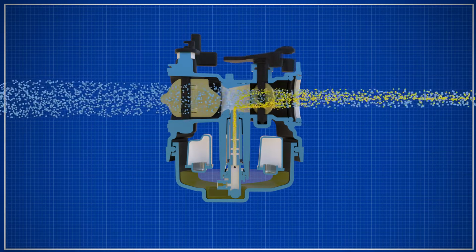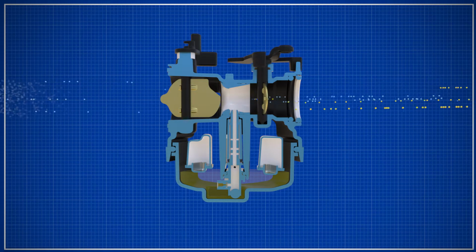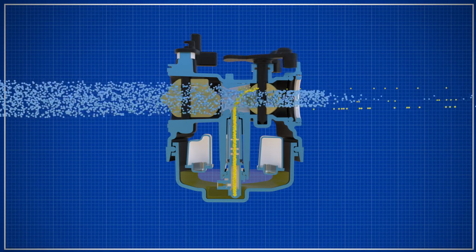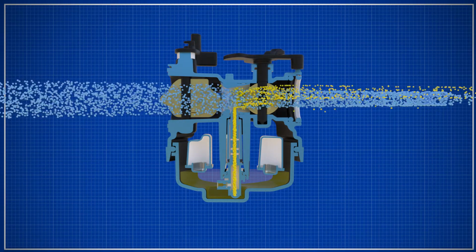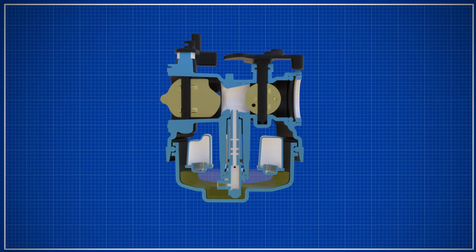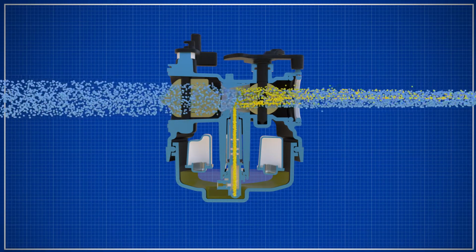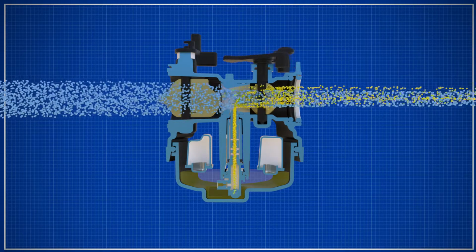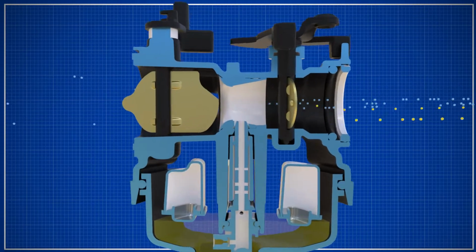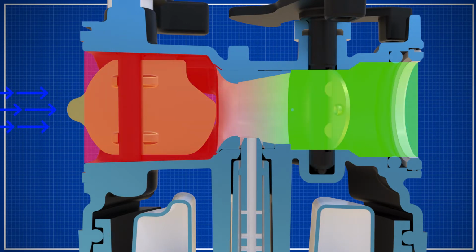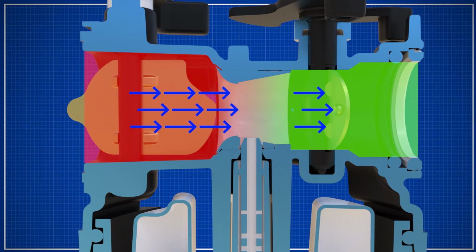Briggs and Stratton carburetors are frequently assembled from materials that include different features and configurations. However, they all operate on the same theory of operation: Bernoulli's principle of fluid flow applied to carburetors. To make a carburetor function, it is necessary to leverage the help of atmospheric pressure. This is where Bernoulli's principle is applied. Bernoulli's principle claims that as the speed of a fluid increases, the atmospheric pressure decreases on that fluid.